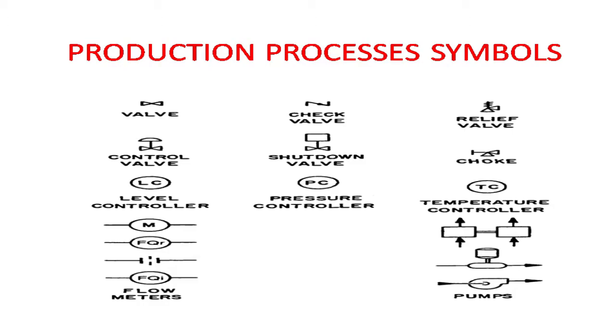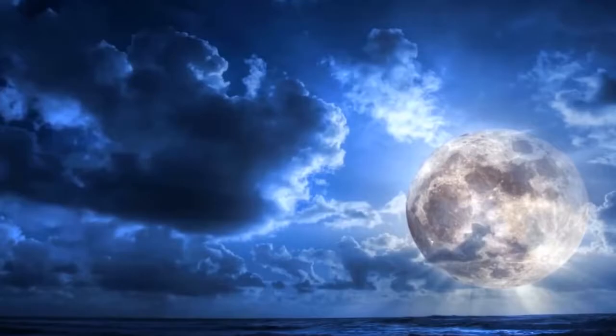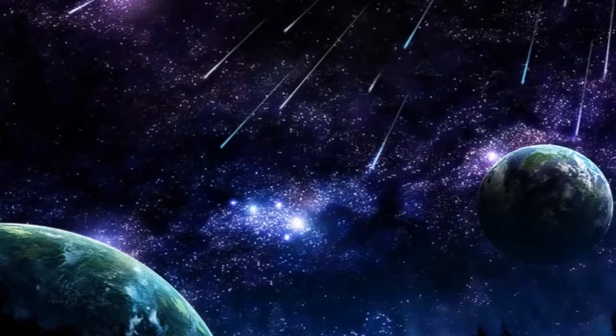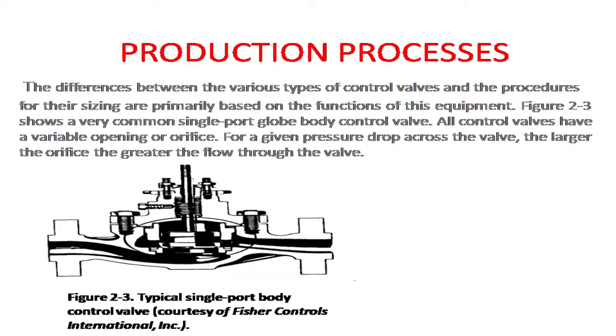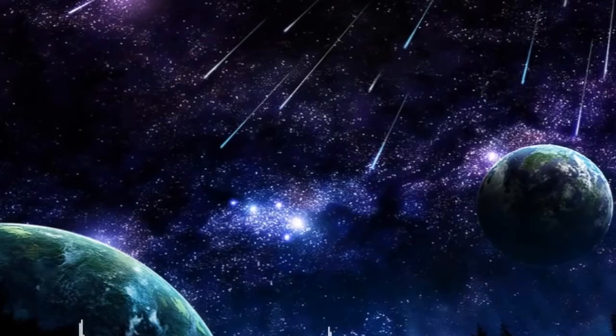Level control. Now, for tanks, storage tanks and everything, and even some pressure vessels, there's need to do what we call level control. We want to control the gas-liquid interface or the oil-water interface in process equipment. This is done with a level controller and a liquid dump. The most common form of level controller is a float.